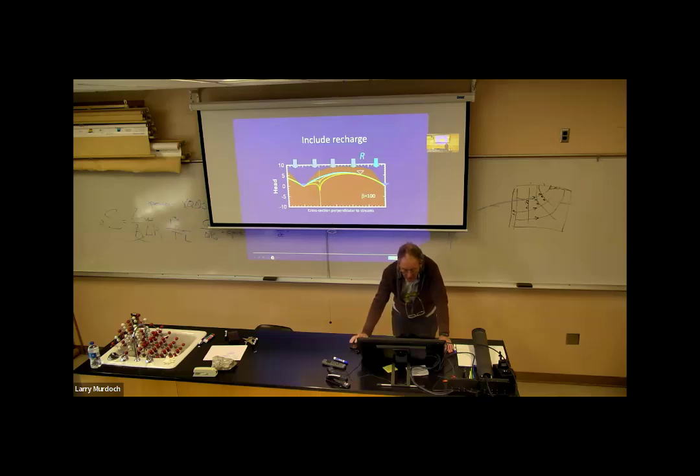And we have another little increment in time. And what we can see now, the hydraulic head looks like this. There's the divide. So recharge that comes into the aquifer on this side of the divide goes to the well. Recharge that comes in over here still is going to the stream. So at this point, though, you can see that the hydraulic gradient here at the stream has changed.